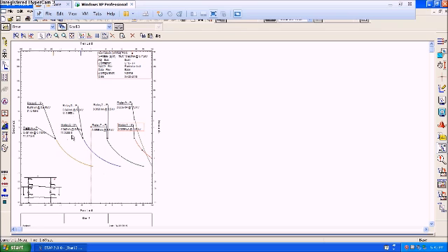We will not consider the relays which are on the upside, because we have to show the connection between these two relays. Suppose a fault occurs here below relay 6, then relay 6 will operate, relay 5 will operate, and the main problem will come when a fault is created in between relay number 6 and 5.